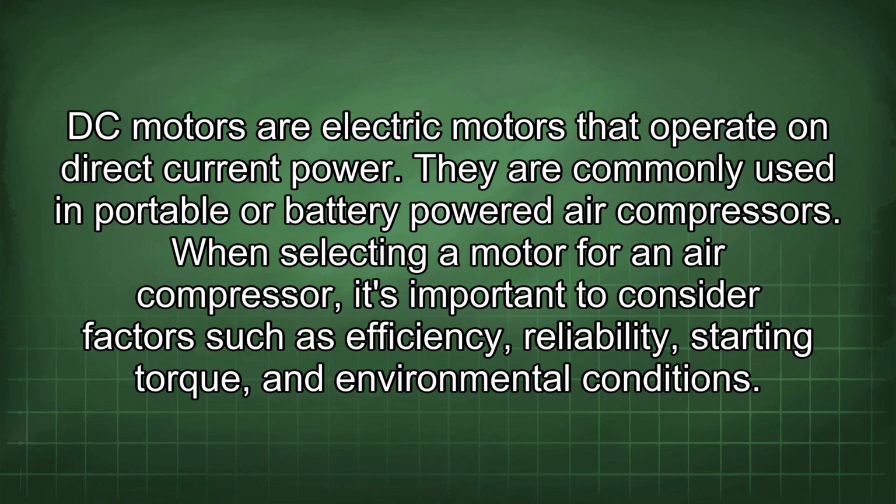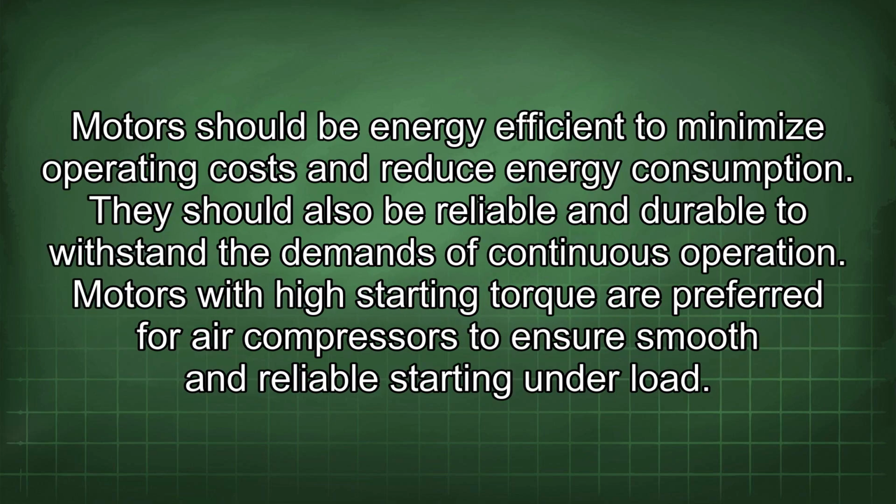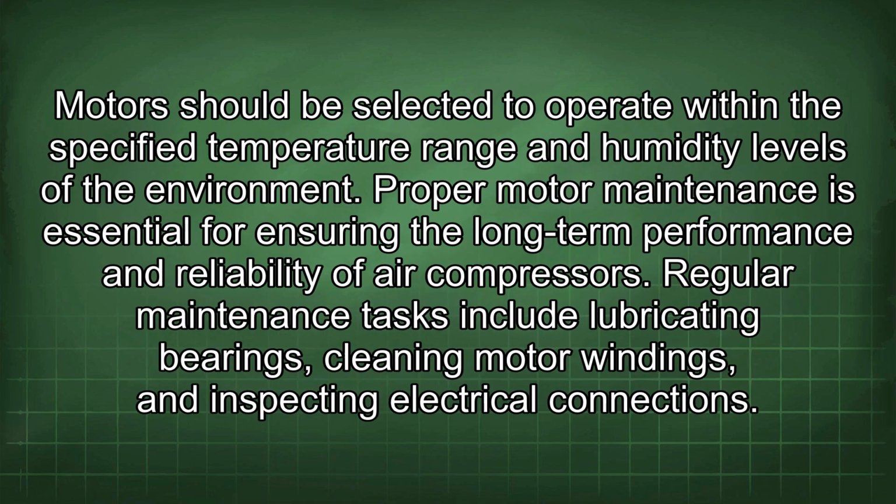When selecting a motor for an air compressor, it's important to consider factors such as efficiency, reliability, starting torque, and environmental conditions. Motors should be energy efficient to minimize operating costs and reduce energy consumption. They should also be reliable and durable to withstand the demands of continuous operation. Motors with high starting torque are preferred for air compressors to ensure smooth and reliable starting under load. Motors should be selected to operate within the specified temperature range and humidity levels of the environment.